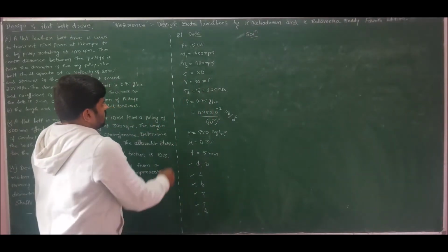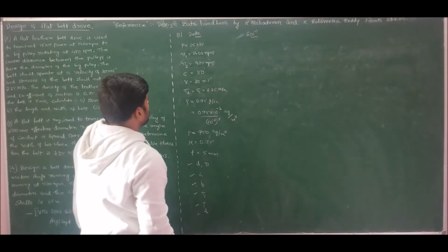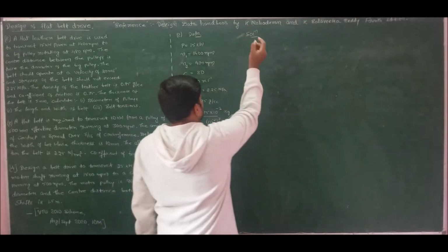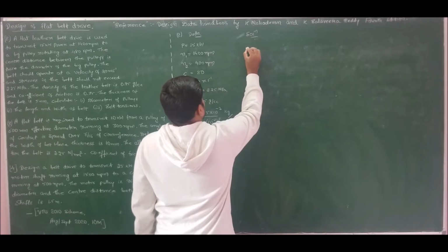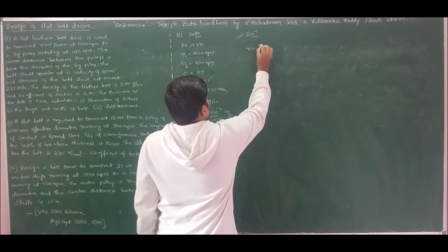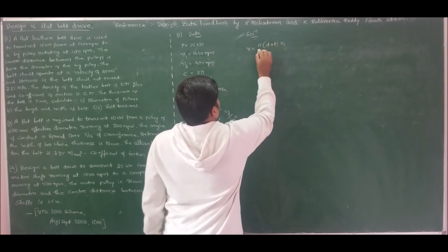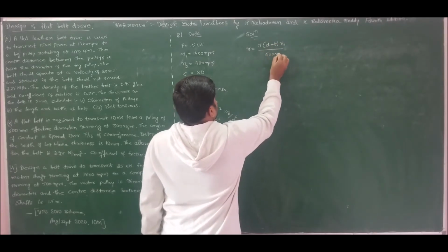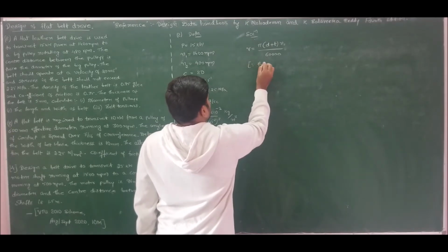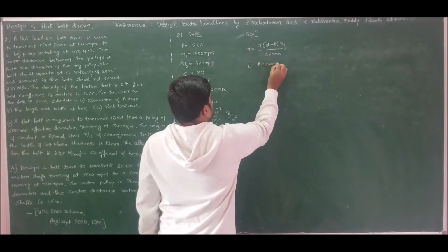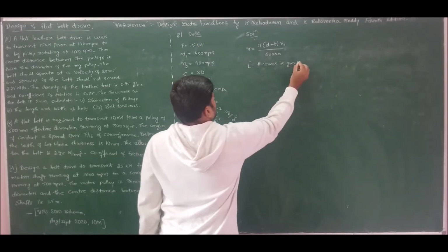If I move to the solution, first let us make use of the velocity equation and find the effective diameter of the smaller pulley, that is the diameter of the prime mover. Since he has given the velocity v, I can write this as pi into d plus t into N1 divided by 60,000. This is because thickness is specified, so I should consider the thickness without fail.